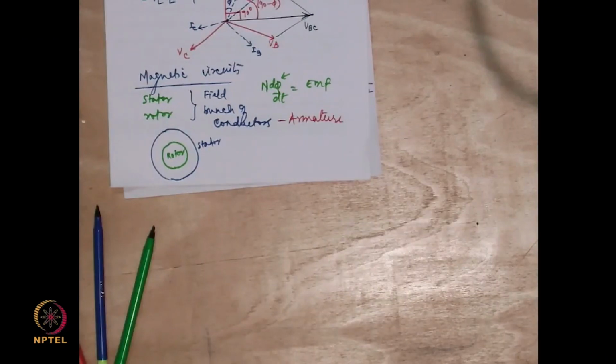So if I am having the air gap, clearly it is not going to pass the magnetic field lines as well as the ferromagnetic material. The ferromagnetic materials generally have something called permeability, which is a very, very high value for them. It is a material property and it is going to allow the magnetic field lines to pass through them very easily. Whereas the non-magnetic materials like air or wood or any of them will not allow the magnetic field lines to pass through so easily.